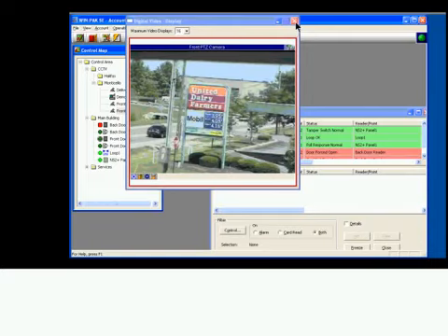Just from a managed video point of view, if we're having any kind of hard drive failures or anything, we'd like to be able to send alarms on the status of the DVR, as opposed to actually monitoring it for motion situations. We're just looking at actual technical situations. Right. You can schedule the Winpak software to dial out, but I don't know if the DVR itself has the capabilities built into it based on trouble. But Winpak can be set up so that every 2 hours, every 4 hours, it dials out to the site and retrieves the information. And then based on an alarm closure or something happening on the DVR, you can retrieve that information as well through that module.